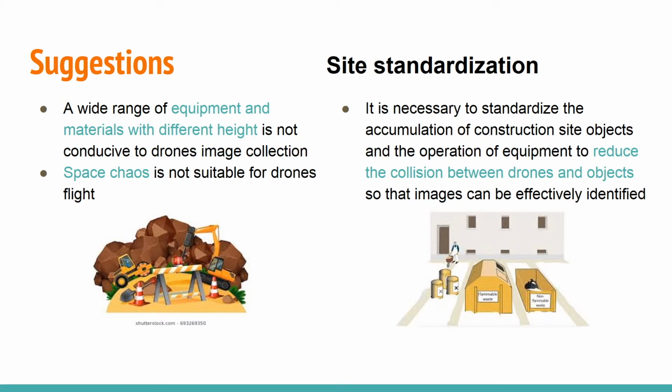Now here comes two suggestions. The first one is site standardization. A wide range of equipment and materials with different height is not conducive to drones image collection, and space chaos is not suitable for drones flight, so it is necessary to standardize the accumulation of construction site objects.